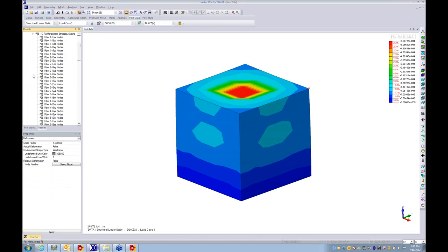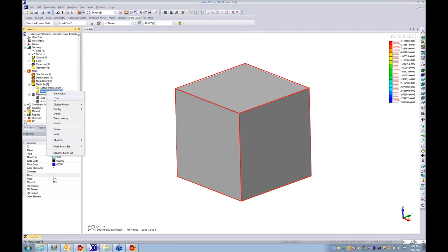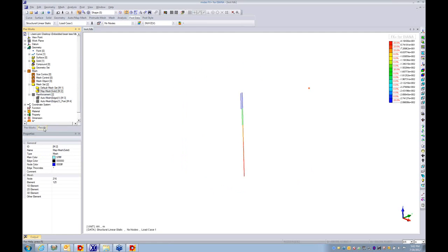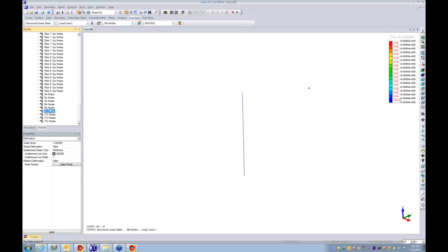And here under 1D, you can see all the fiber reinforcement, say in the fiber position at the corners. In the middle plane, stresses, strains, axial forces, if I hide my box. And if you have some eccentricity and others, you may get your bendings as well. And corresponding relative tractions and displacements. These are the relative displacements, and these are the tractions.